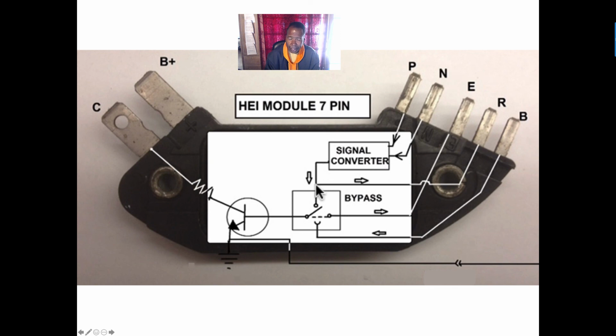You can see here, this is a much clearer picture. You can see here, I have a digital signal going here to the base. Once I get a positive signal on the base, I'm going to, from the collector to the emitter to ground, trigger the coil. See right here? This is going to the coil negative side. I'm going to trigger the coil.